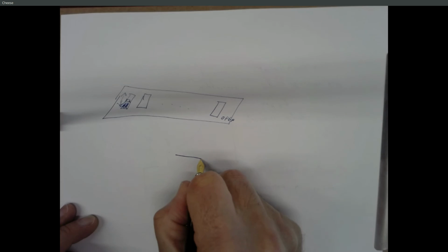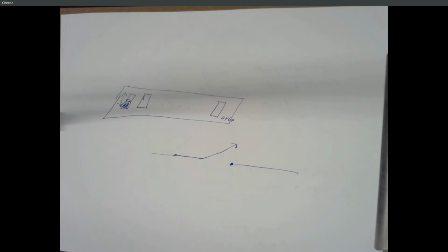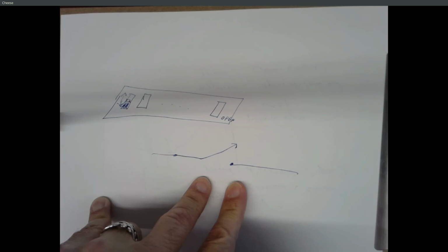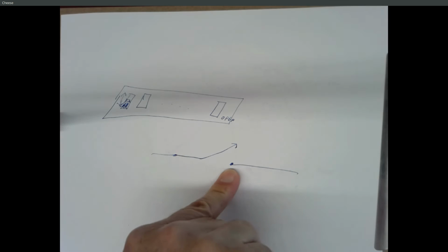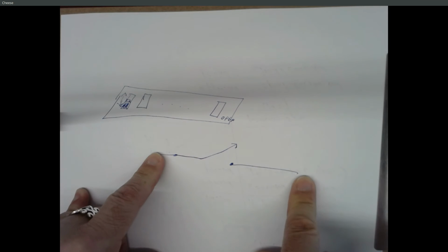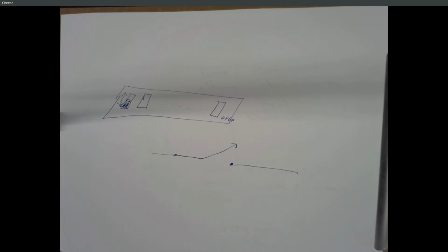So how do we draw pictures of this? We usually represent these switches like this. And it's a throwback to the idea of a push button, right? This is what the button pushes down on. This is sort of normally open. And when you push the button down, this arrow comes down and makes contact with this side of the metal, and now this point and this point are connected. So in this position, these two ends are disconnected. When you push this down, they're connected. But normally open push button, normally closed push button, sliders, rockers, lots of different ways to implement this.